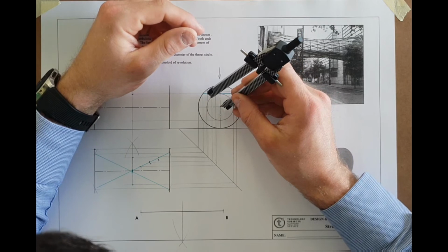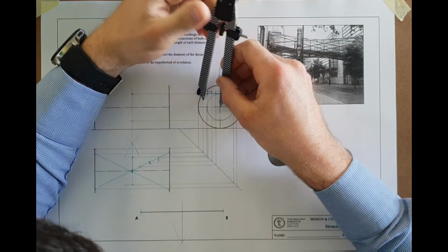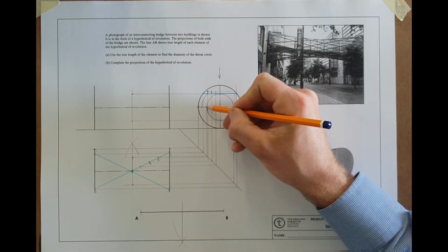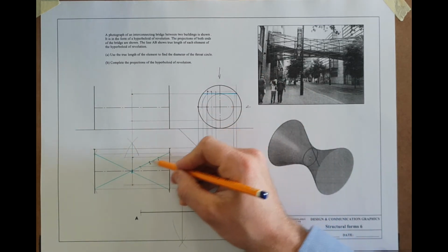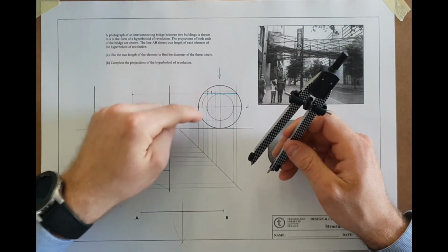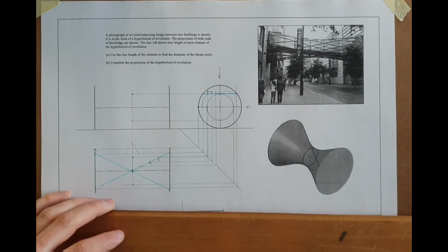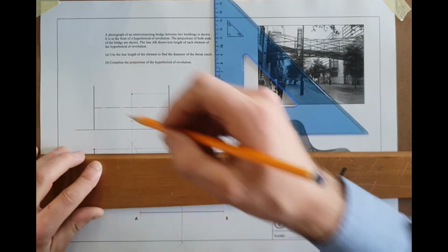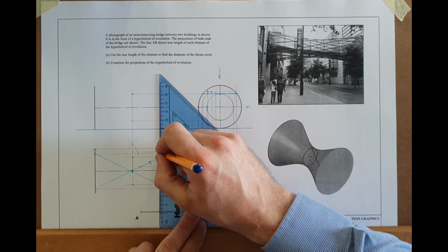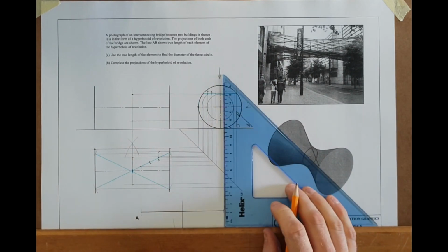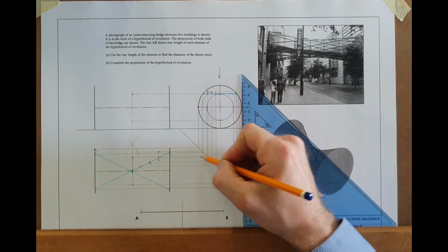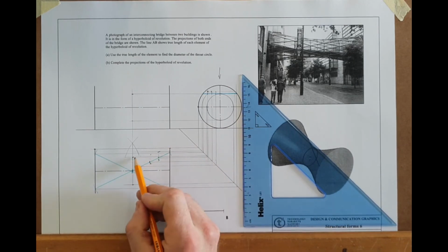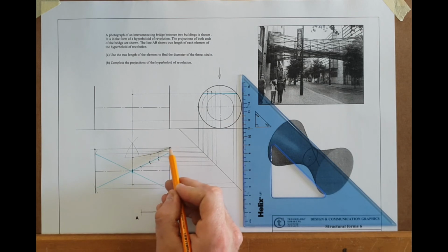So we're going to rotate them down until they're in a position that we will be seeing them in plan, from the base circle to the throat to the base, which is here. We can rotate point 3, point 2, point 1. And what does that rotation look like? So point 3 in its new position, in its rotated position on the extreme is somewhere here. That's point 3. Do the same for 2. Rotate, project and rotate. Then you get point 2 and point 1. There we go.